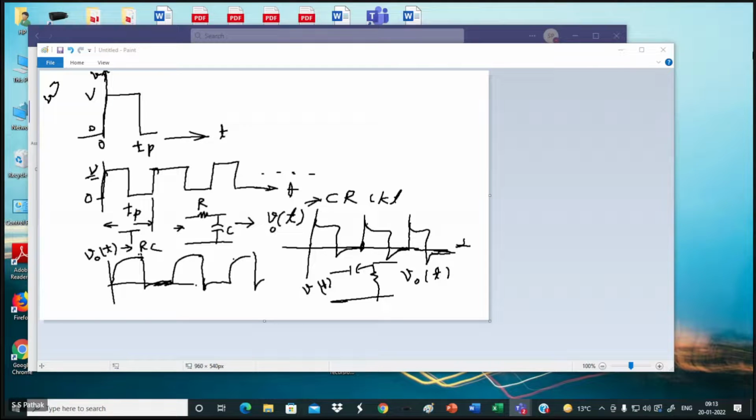So you have seen that. Then I also explained everything depends on this time constant, this exponential rise that you are showing. In this case, it is exponential decay. In case of your RC circuit, the exponential decay is controlled by e to the power minus t by tau, where tau is your R into C in both the cases. Exponential decay is this, and what about the exponential rise?